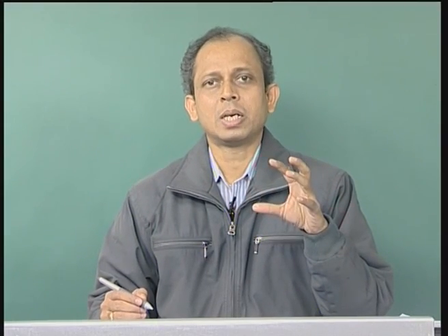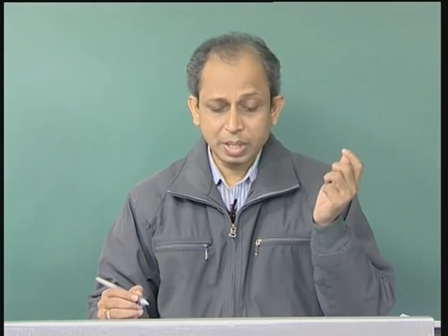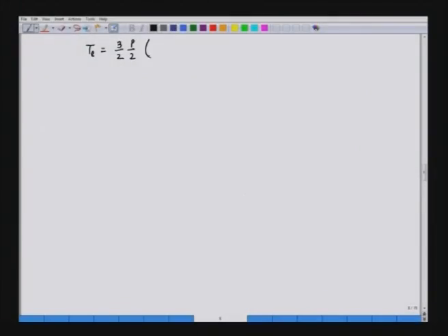The only thing is that the rotor has been replaced by a permanent magnet. So, in that case the equation is psi d s I q s minus psi q s into I d s. So, we will be replacing all these expressions in this equation.